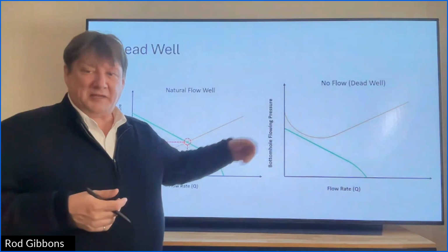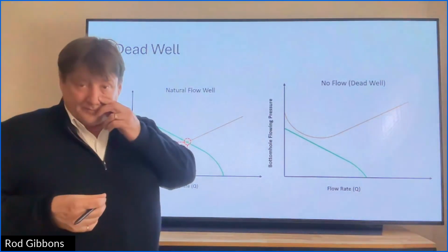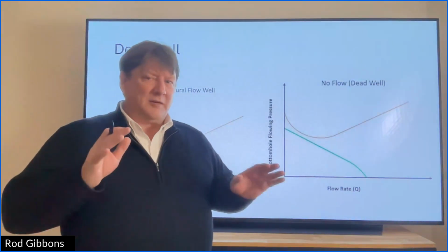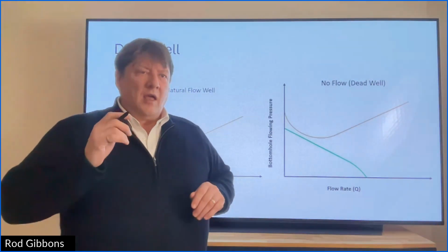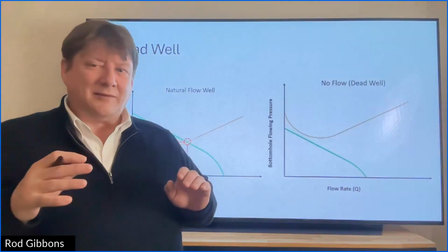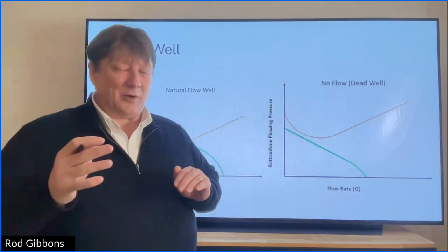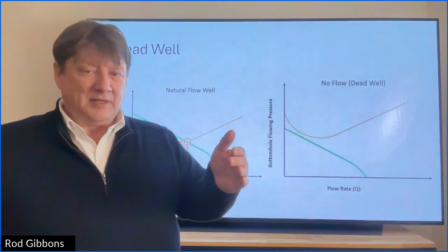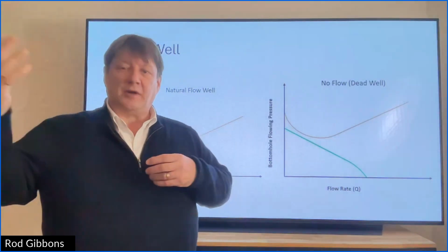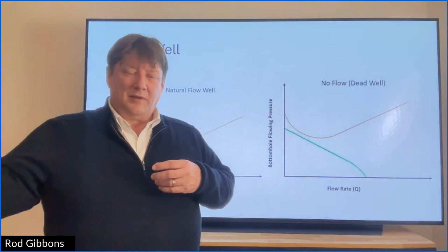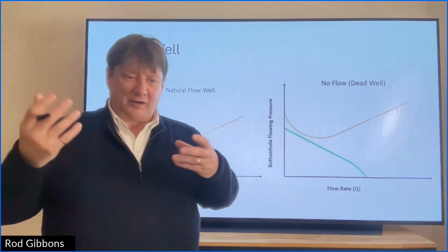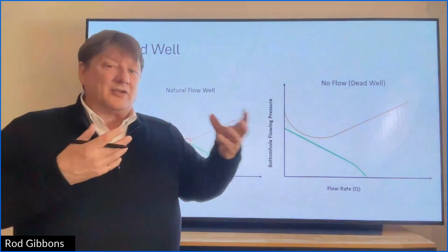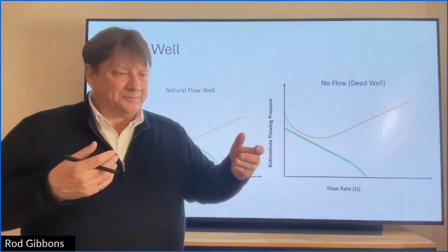Almost all wells would be dead wells for natural flow. And I say dead wells, just need to be a little bit careful on that because there's two things when we talk about dead wells. One is a dead well, it won't flow into a production system. So into a flow line, into a gas plant or an oil battery where it can be separated, where the oil, gas, and water can be separated. There's a certain pressure it needs to get into that system.